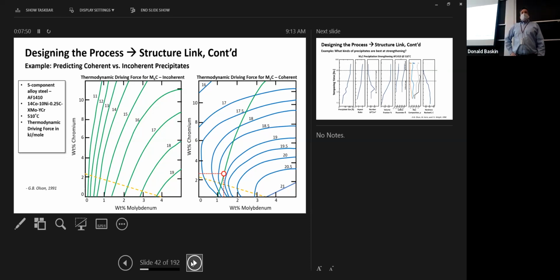Now, I want you to think of this in terms of a design space, and we're going to talk more later about design spaces and how that applies to geometry. This is a two-dimensional design space. You've got two variables, the amount of chrome and the amount of molybdenum. This yellow dashed line is the stoichiometric ratio between those two in the material. Compositions along this line were investigated by a graduate student at Northwestern. I think it was Gary Campbell, but I'm not 100% sure. Those materials were mixed, cast into little ingots, heat treated, and then hardness measurements were taken. So that part was experimental.